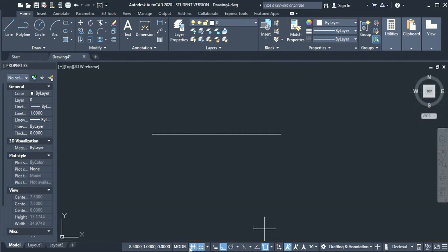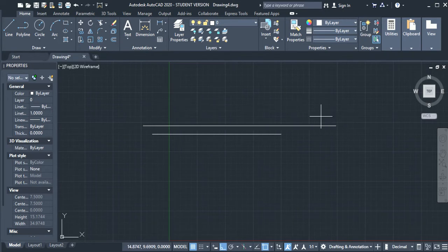We're going to leave the grid on, so that turns it off, and this turns it back on. We're also going to leave snap on. If we turn snap off, we can draw a line anywhere. It doesn't really matter, see how it's a very fluid motion. If we turn that on, now it's very incremented. It snaps to the little grid points. I'm going to hit E for erase. So first escape, then E for erase.